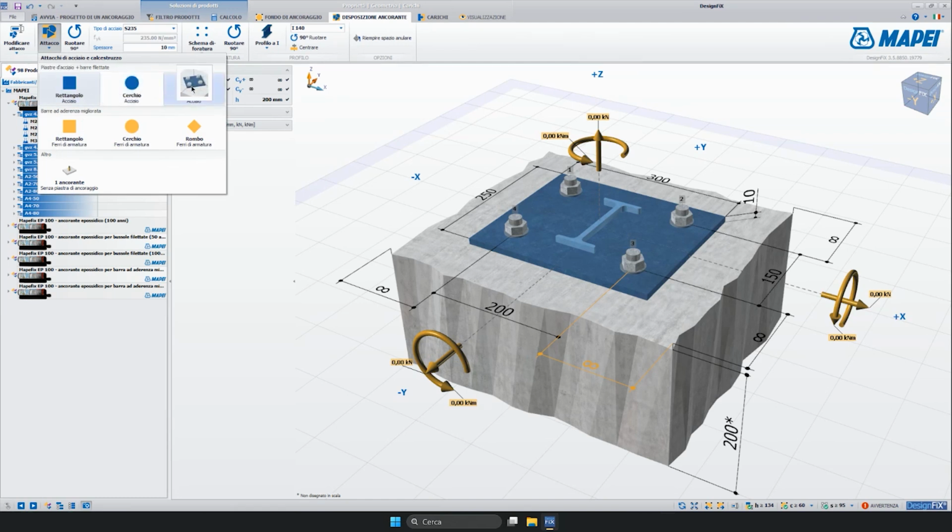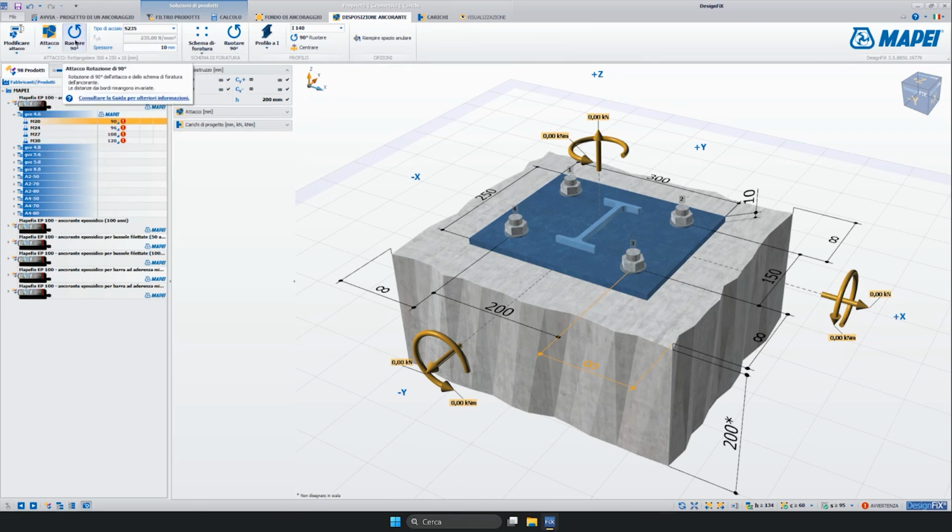Amongst the other options available, we also find rebar, without the use of steel plates, and the special case in which we want to create an anchor for a single steel element. It is also possible to choose the rotation of the plate in order to align its length along the calculation direction specified. The user can specify the steel type used for both the vertical steel element and for the base plate, with the option to also define the thickness.